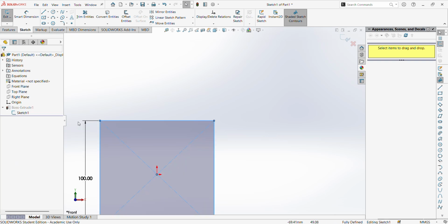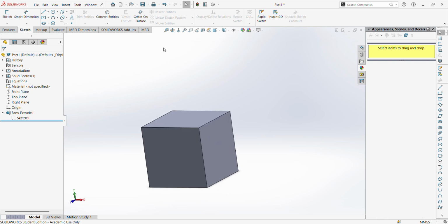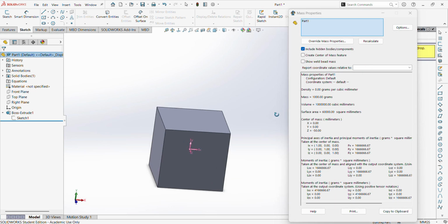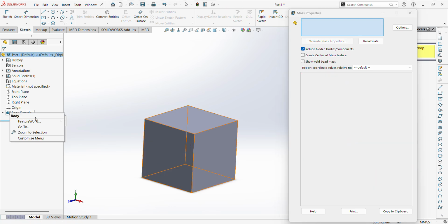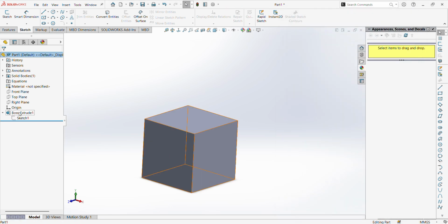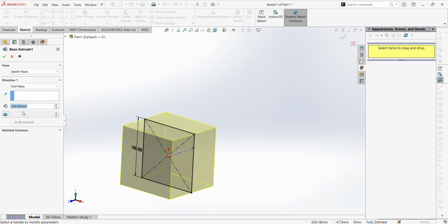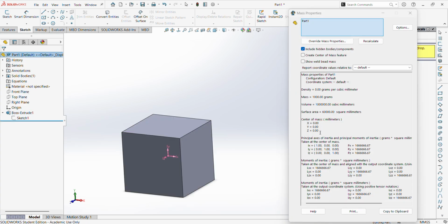I would have to make one change though with our extrusion to fully center them out. And if you know a little bit about SolidWorks, you'll know what I mean. That's that mid-plane extrusion versus the blind. You can see our z-axis is at minus 50 for the center of mass, and that's due to this extrusion that we did. And that should make sense because we sent the extrusion out one direction when our origin point was here. But if we mid-planed it, see how that shifts everything? Check our mass properties again. We see everything zeroes out.